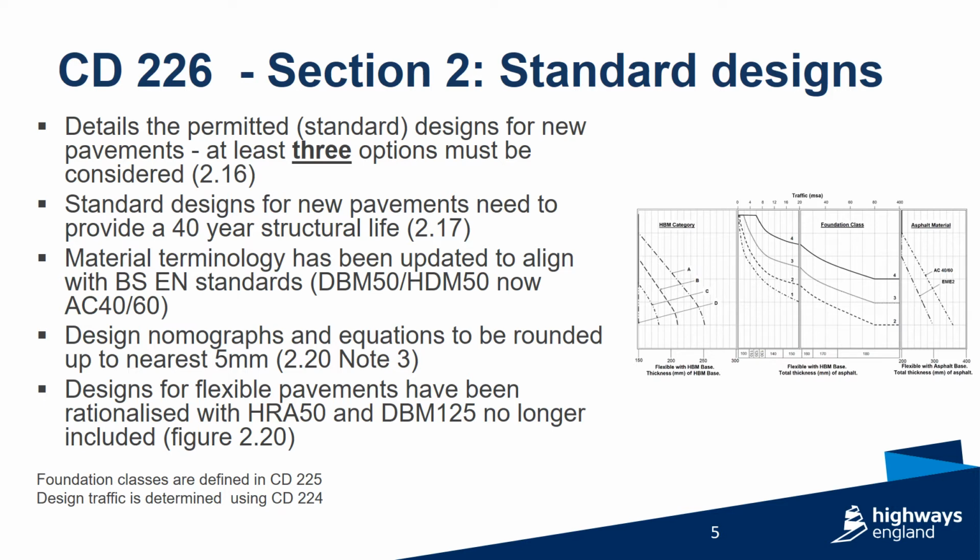Material terminology has been updated to align with British and European standards. For example, DBM 50, HDM 50 has now been renamed AC 40/60. Clause 2.20 Note 3 requires design nomographs and equations to be rounded up to the nearest 5 mm. Previously, in HD 26/06, this was to the nearest 10 mm.